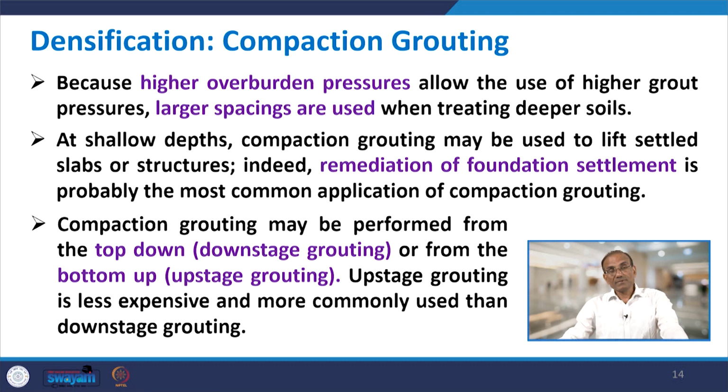Continuing with compaction grouting, higher overburden pressure allows the use of higher grout pressures. Larger spacings are used when treating deeper soils. So, naturally, when you go to a higher depth, a larger amount of grout will be required. At shallow depth, compaction grouting may be used to lift settled slabs or structures.